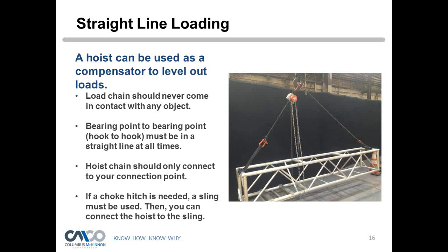A lever tool works just fine as well, and we have another webinar that basically shows how to do this with the lever hoist. But you've got to stand pretty close to the load. You're right up against it, because in order to operate that lever hoist, you've got to be right up there against the load. So you do have a little bit more danger involved by doing that. Very good question, though. Thanks.